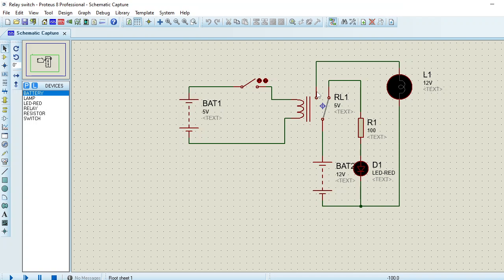And for the normally closed, by default the circuit is always complete, and the current flows to the load. So without the signal it is always on. We're going to demonstrate it with a simulation. When an input signal is applied, the coil breaks the circuit, and therefore turns it off. I'm going to illustrate what I'm saying with a very simple simulation.